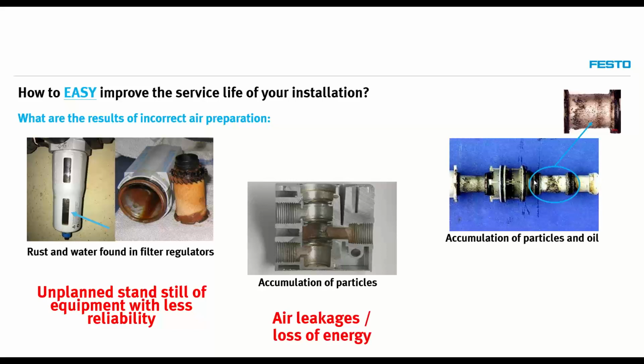The second thing is that it can generate leakages, a loss of energy, because a leakage of compressed air at the end of the day is a loss of energy which you generated during the compressor stage, because particles can result in bad sealing of your seals in your valve body. Additional wear and tear is of course obvious, because a particle can result in an abrasive movement.